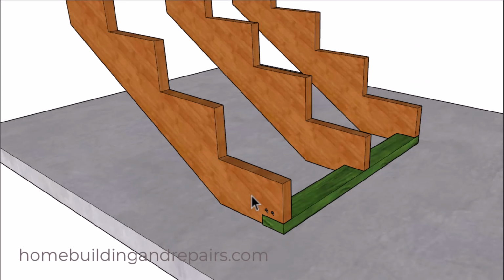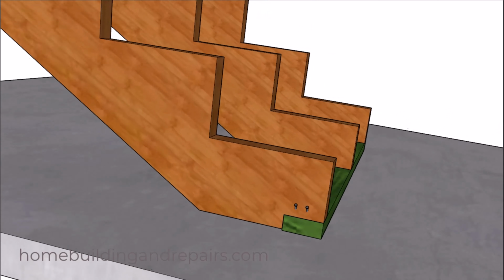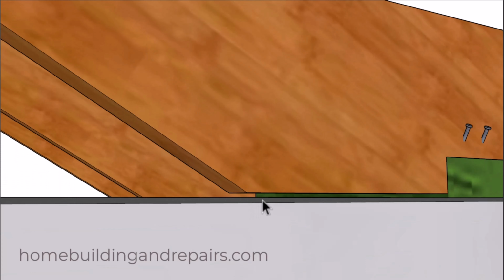And the biggest arguments I have against this is supporting a notched piece of lumber at the front and not the back, or the fact that you have an untreated piece of lumber touching the concrete, and that might not be a problem on an interior stairway. However, you would have that problem if there was a gap between the bottom of the stringer, and I see this all the time.